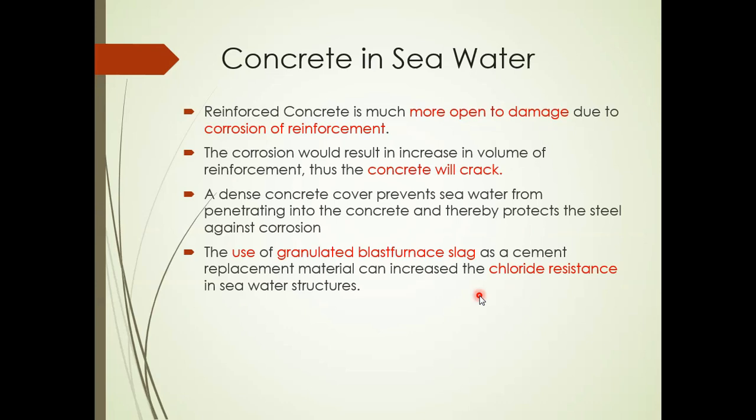A dense concrete cover prevents seawater from penetrating into the concrete and thus will protect the steel inside the concrete against corrosion. Also, using granulated blast furnace slag as a cement replacement material can increase the chloride resistance of the concrete against seawater.